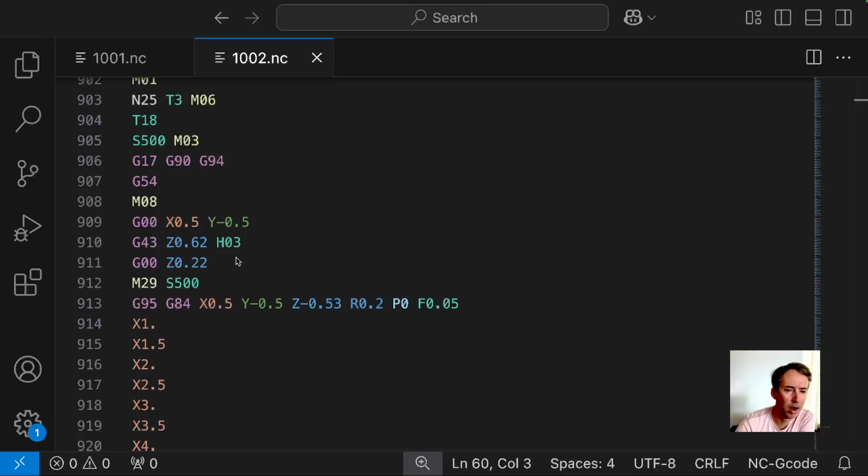All right, so I also wanted to look at this G95. Here is showing how we can use G95 instead of your typical G94 for tapping. G95 gives you feed per revolution. So that means on a tap, you're actually just putting in the tapping thread pitch as your feed rate. This is the Phoenix style with the M29.